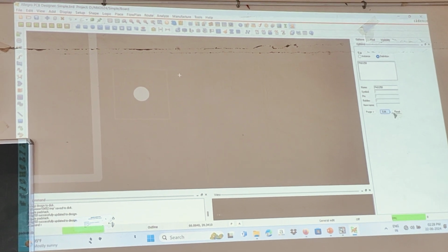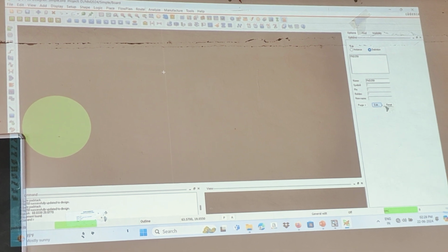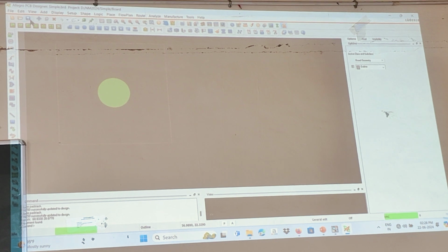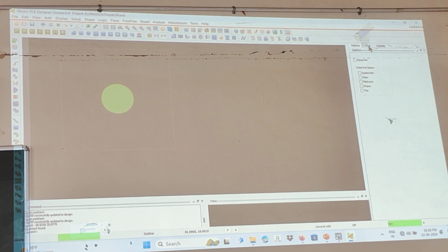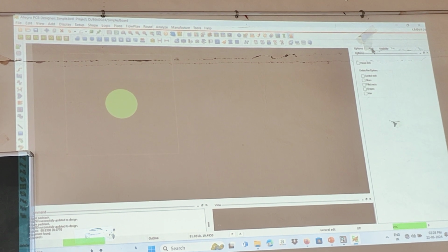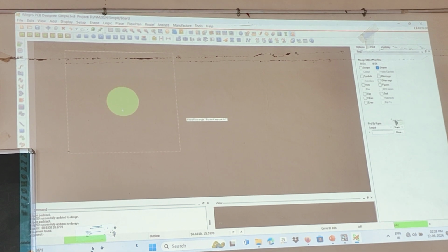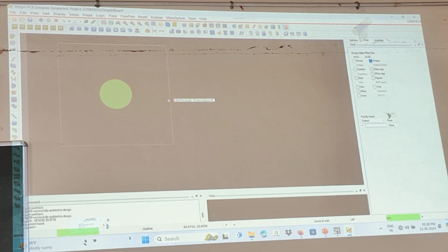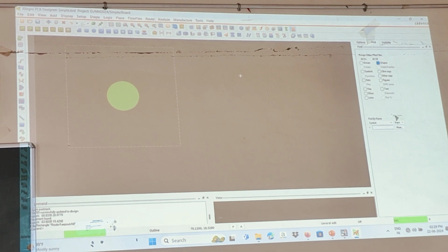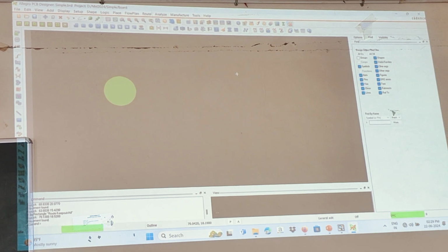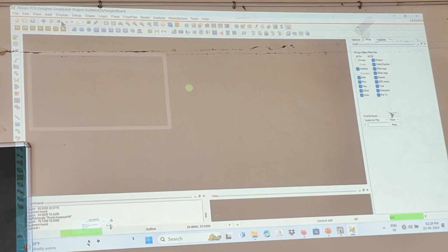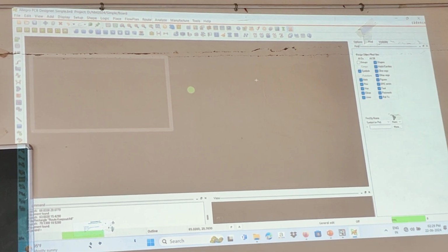Okay. Here we have the keep route class over here. We no need of this, so I'll just delete it, or we can disable. To do so, I'll just select delete and click find. In that I'll select shapes and then go to the option. If you move the cursor, we can see it has been highlighted. Once it is highlighted, that alone will be deleted. Just click once and click another click outside in the workspace, then it will be deleted. This is the same whenever we delete any class or subclasses or any pins or anything else. We have to select delete and select what we want to delete, and after that click outside of the workspace area.